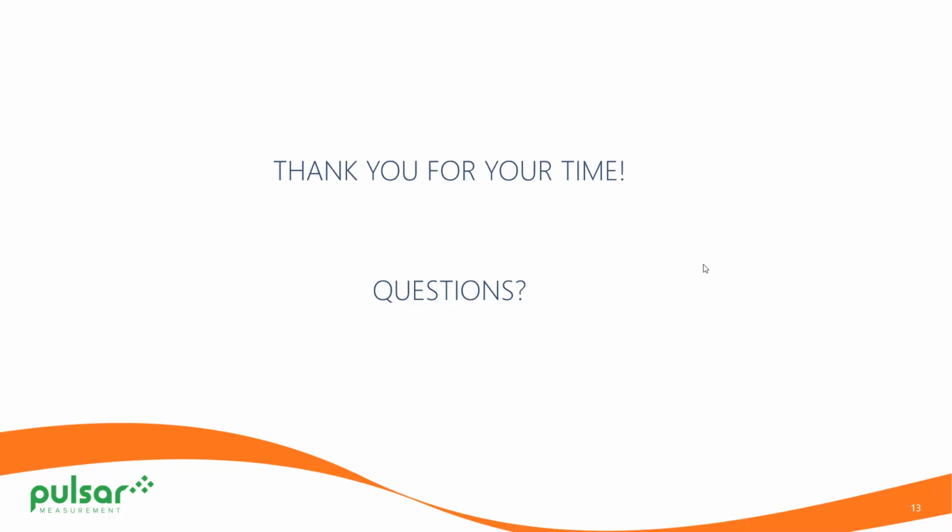I'll wait you out. Oh, is there a hybrid version of the DFM and TTFM? Another good question. Not at the moment, but I can tell you it's something we're taking a serious look at. I've heard of hybrid versions in the field from other manufacturers. For those of you that don't know what we mean by hybrid, it's a combination meter. Let's take dredging, for example. You'll have a rush of clean water coming through a pipe. That's transit time technology. Then all of a sudden you'll get a whole bunch of mud and other junk. That's Doppler technology. A hybrid meter would be one that could detect both and would know when to switch from Doppler to transit time.